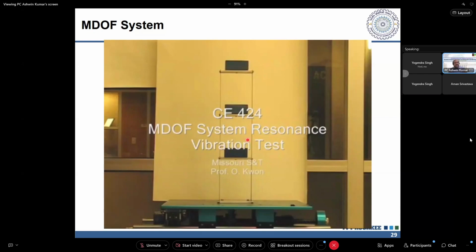If you find the solution for the displacement time history, another usage is to find out the natural frequency or the natural time period of the system. And we can also find the displacement time history of that system when it is set into free vibration. Then we looked at a single degree of freedom system subjected to an external force, let it be P of t. If I have a P of t which is a harmonic motion, sine omega bar t, like when some machine is functioning, we know how the classical form of the equation of motion is solved.